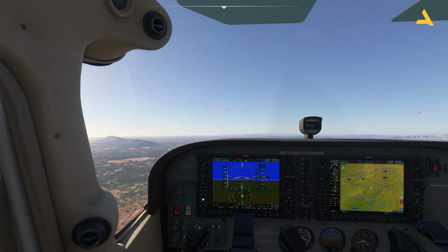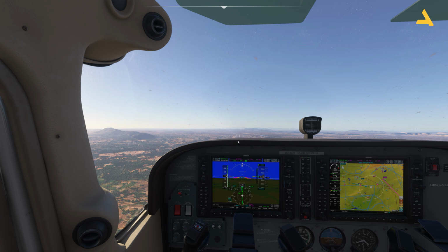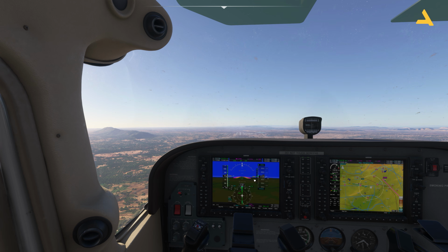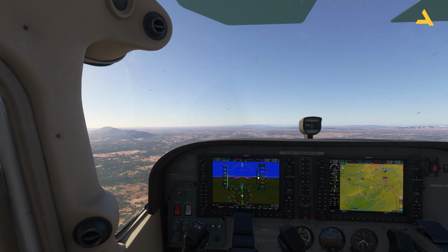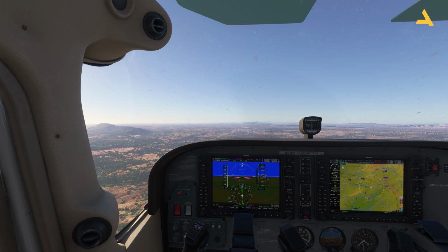Now as the approach mode is on, as you can see, this localizer thing is coming, which means the plane is actually following the localizer, and this glide slope has started to appear. So now the plane is actually following this glide slope. It's now time to reduce the thrust and start extending the flaps.